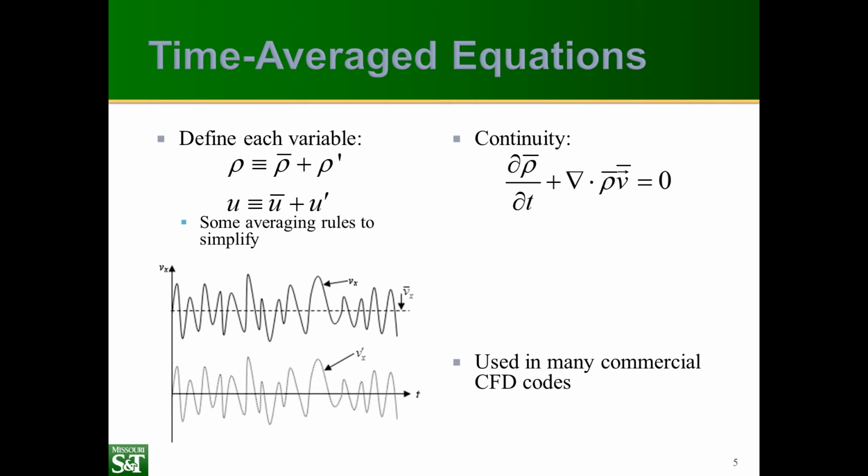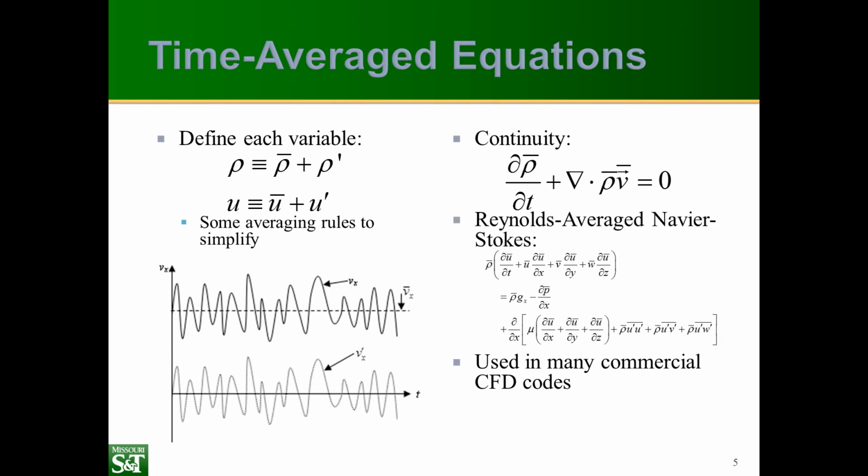Here there are no additional terms or anything, no real surprises, but we also end up with the Reynolds averaged Navier Stokes equations. The Reynolds averaged Navier Stokes equations are called Reynolds averaged because we have these additional terms that account for what we call covariances between the velocity fluctuations, where we have to average the product of the two.